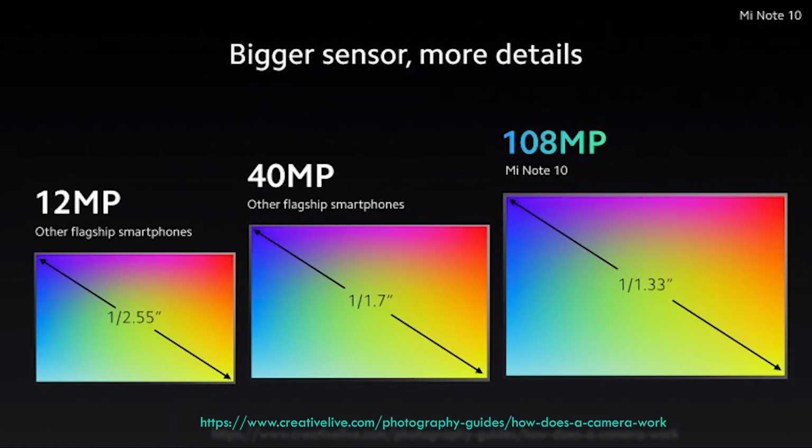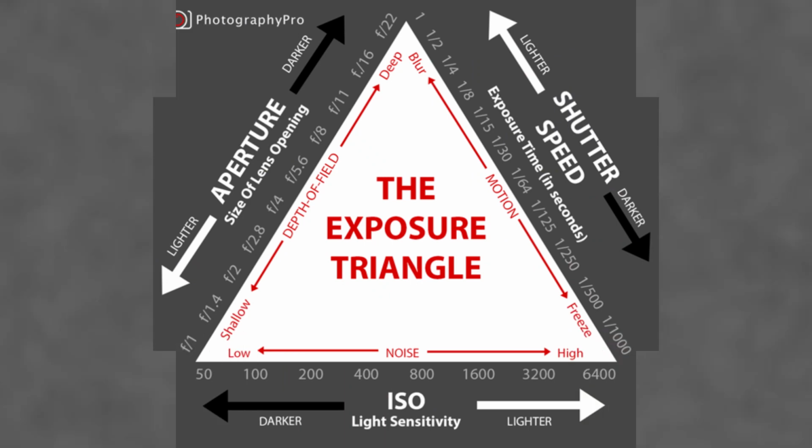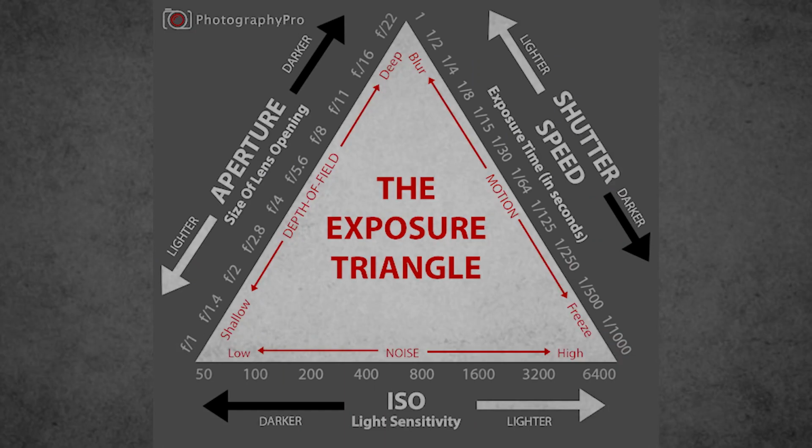Putting the information from all the pixels together, the computer is able to approximate the shapes and colors in the scene. If each pixel is gathering light information, then camera sensors with more megapixels are able to capture more details. That's why manufacturers often advertise a camera's megapixels. While that is true to some extent, the size of the sensor is also very important. Larger sensors will gather more light, making them better performers for low light scenes. Packing lots of megapixels into a small sensor actually makes the image quality worse, because those individual pixels are too small.